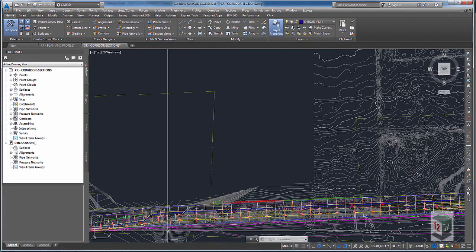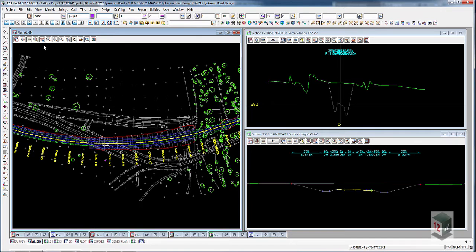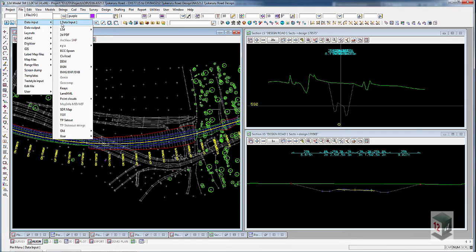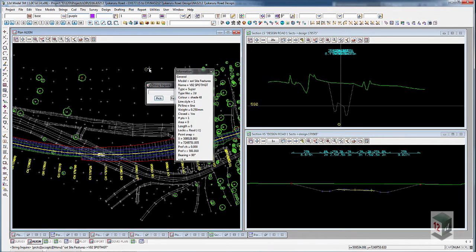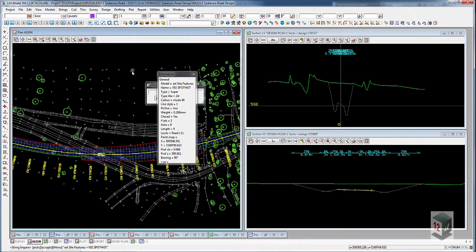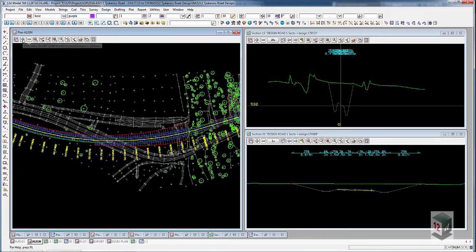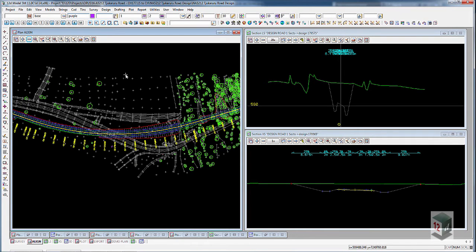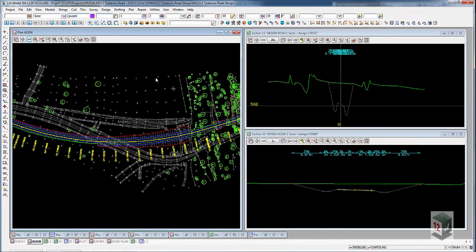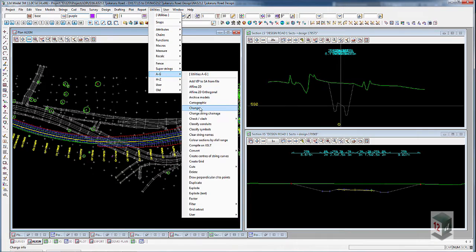So we'll go onto the perspective tab in Civil 3D, and we'll go down to points and point groups. In 12D, you can import points from, say, a surveyor, XYZ, or DTM, DEM, and point clouds as well. What that does is create points, as in Civil 3D. If you want to group them together, it'll be contained under one model anyway. But if you wanted some of these points put onto another model, you just have to copy them.